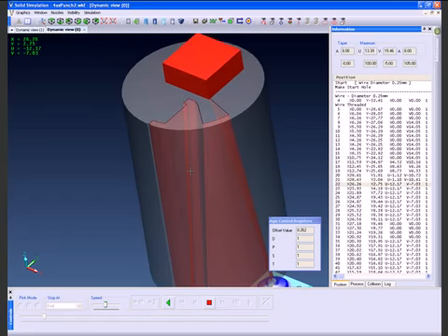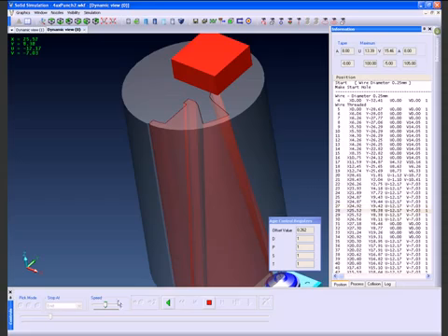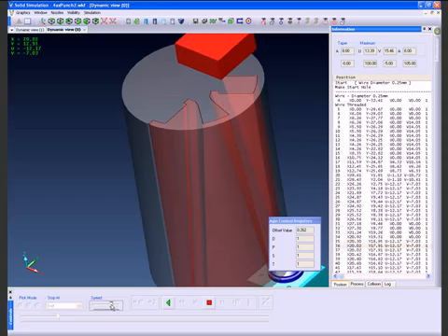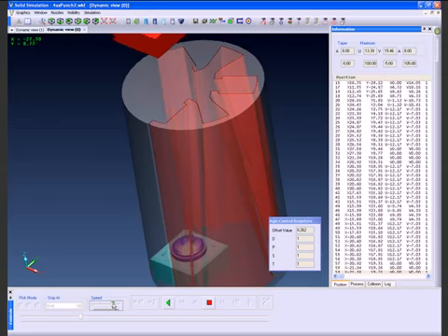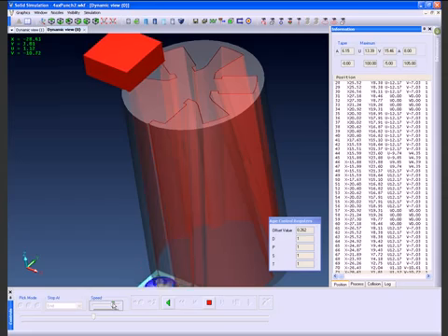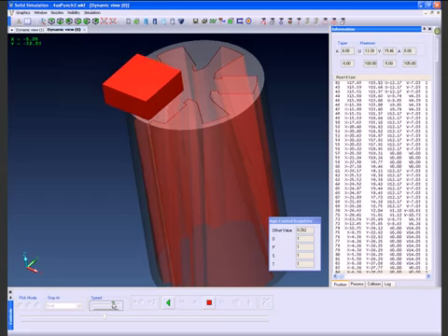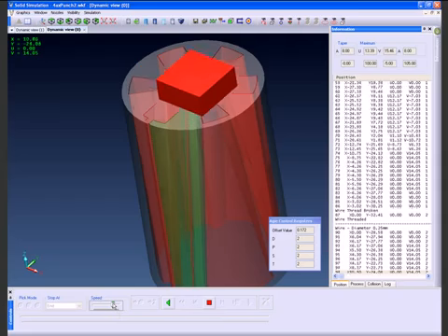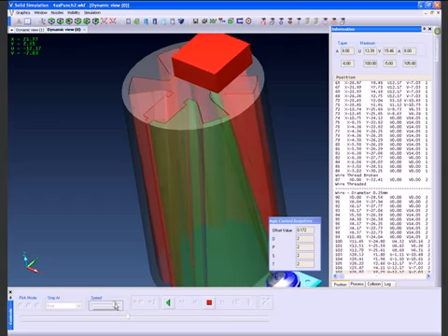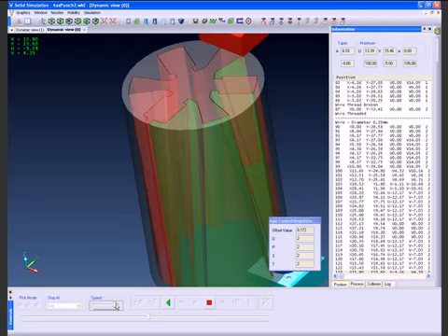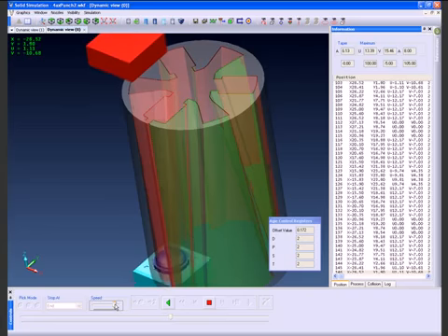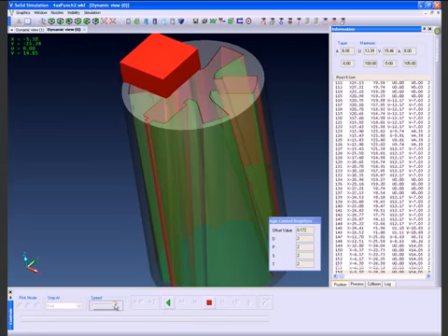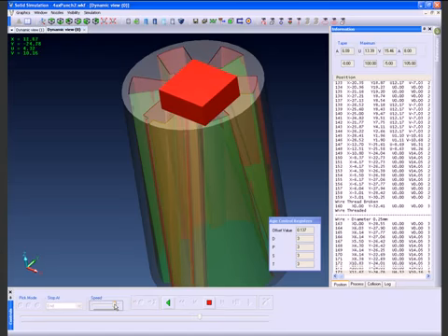This process will then run right the way through till we've actually done all 3 cuts, and we can then move on to what we call a separation dialog, and this will graphically indicate to us whether the actual part itself can be removed from the stock material. We will determine whether we can extract it from above or below, and will also give us an idea of whether we have a trapped situation.